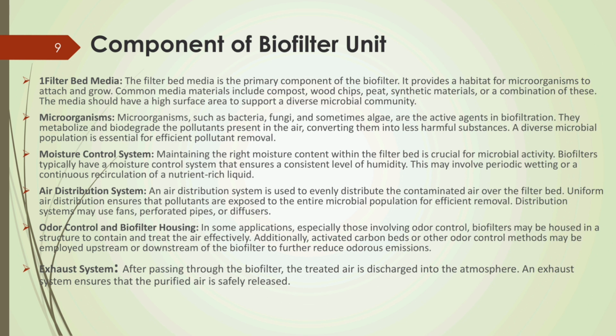Odor control and biofilter housing: biodegradation and metabolism of pollutant present in air by microorganisms create a bad smell for residential area. So a proper odor control system is installed, like carbon bed method, to reduce odorous emission. Exhaust system: after passing through the biofilter, the treated air is discharged into the atmosphere. An exhaust system ensures that the purified air is safely released.